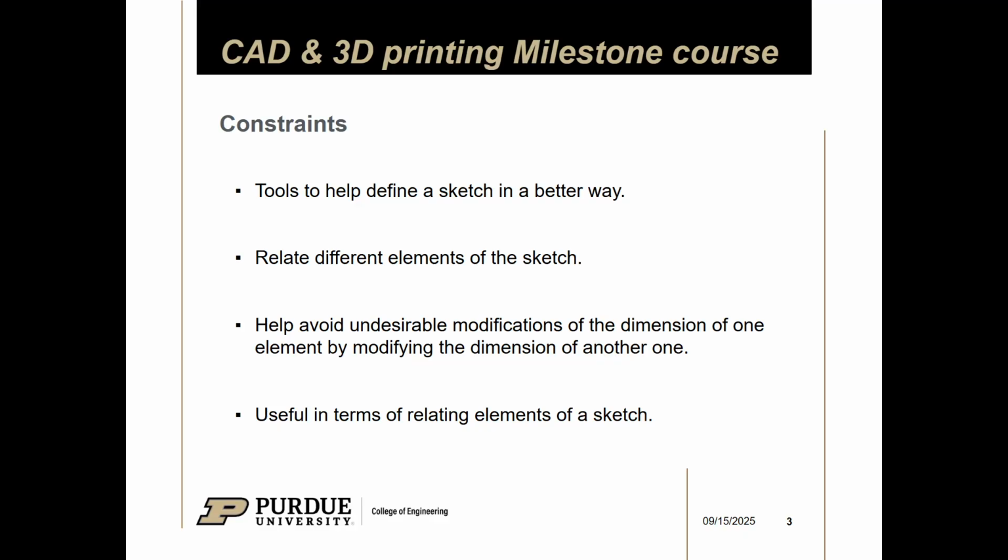But then there's other things that you sometimes wish you could do, and you don't really need to use the sketch dimension tool. When I first started CADing, I didn't really know about them. So when I wanted things to be next to each other, I just started sketch dimensioning things to 0. Do not do that. When I first started CADing, I had no formal training, so I just kind of started doing random stuff. But now that you're here, you can learn things the right way.